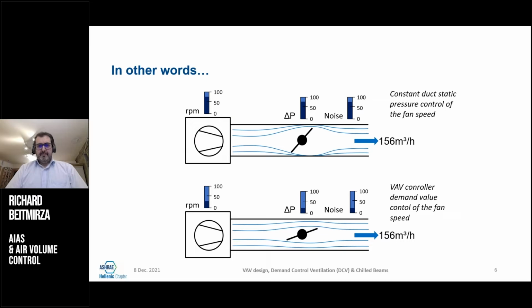Some of the benefits. So we know that as we reduce the pressure and maintain the volume, we're able to reduce the noise. Reducing the pressure also increases the energy savings. So this is almost a win-win. True, initial costs are higher. We use a lot of AC fans, higher cost, higher energy savings. We use VAVs, higher cost, but higher the energy savings. So initial cost is always the issue, but life cycle cost and the benefits outweigh the investments that we have to do initially.